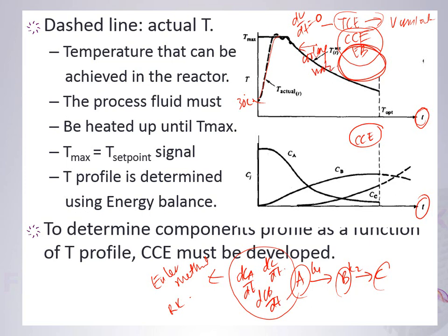Okay, so these are the region when you have steam coming in, the steam plus the exothermic reaction. You cannot let the temperature be too high, or else you will degrade the product. So that's why at this point you must know the degradation temperature of your product. So at this point you start to cool it off.